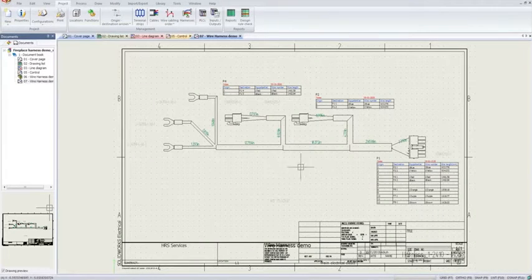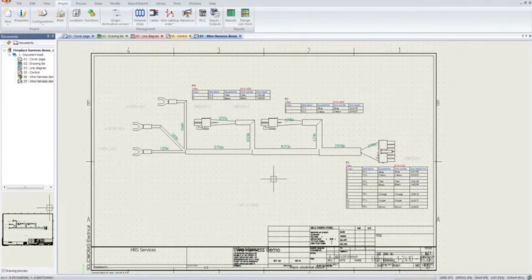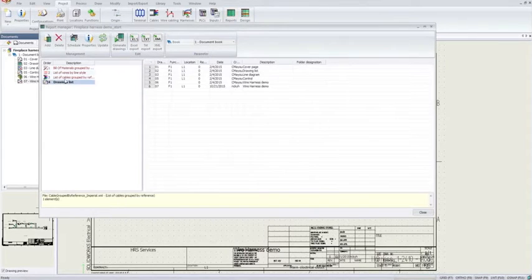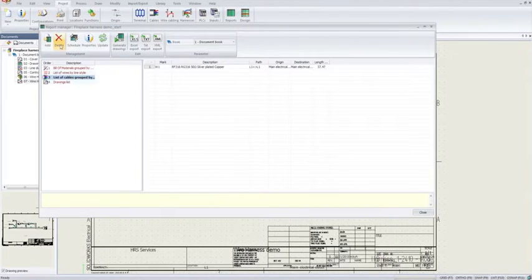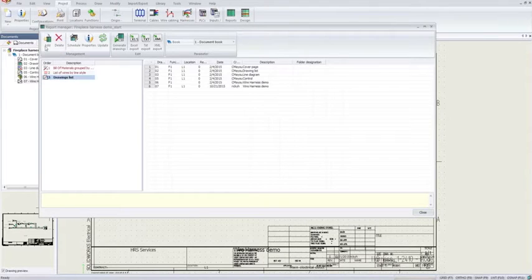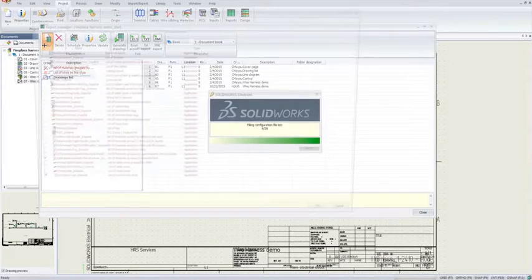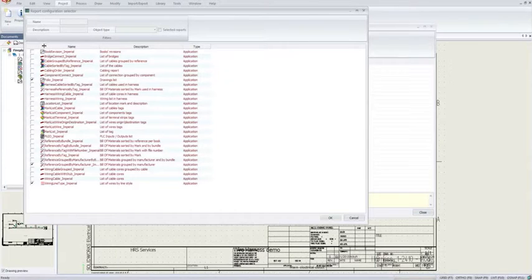Now, once we have all of that set up, right, we have all of our information for our project drawing. We have our connection labels next to our connectors, giving us origin, destination, equipotential labels, right? Now we can generate our reports. If I go to my project and go to my reports, you can add in any list for anything that you need, or remove what you don't need. For example, a list of cables, I can delete that. I can also go to add, and say, for example, I want to add in a bill of materials sorted by mark used in harness, for instance. I can go ahead and check on any kind of report in here.